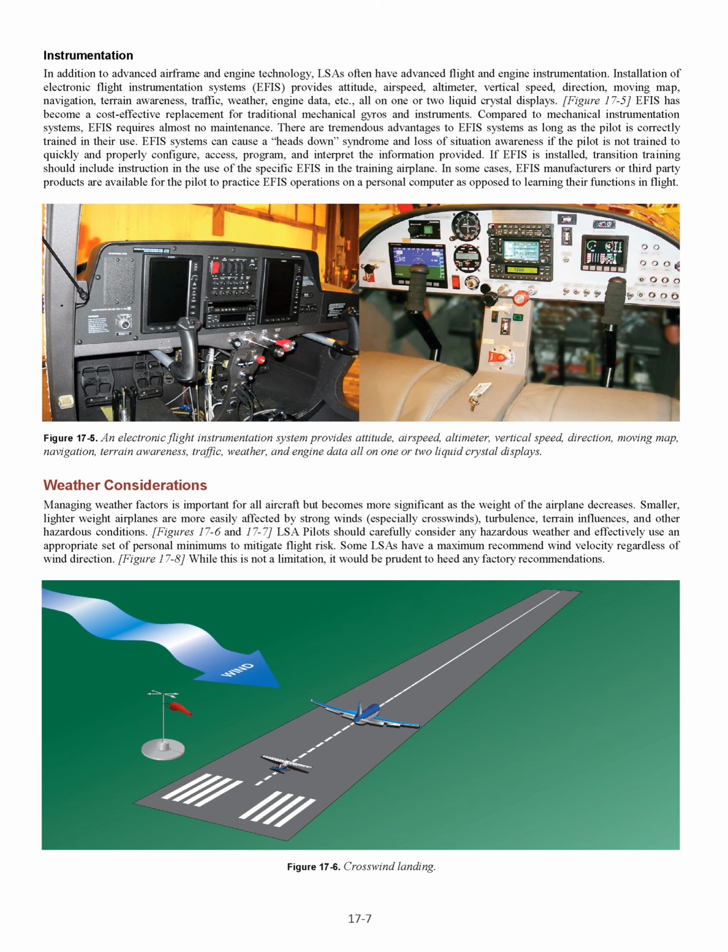There are tremendous advantages to EFIS systems as long as the pilot is correctly trained in their use. EFIS systems can cause a heads-down syndrome and loss of situation awareness if the pilot is not trained to quickly and properly configure, access, program, and interpret the information provided. If EFIS is installed, transition training should include instruction in the use of the specific EFIS in the training airplane. In some cases, EFIS manufacturers or third-party products are available for the pilot to practice EFIS operations on a personal computer as opposed to learning their functions in flight.